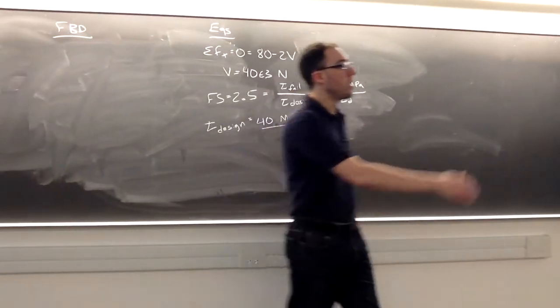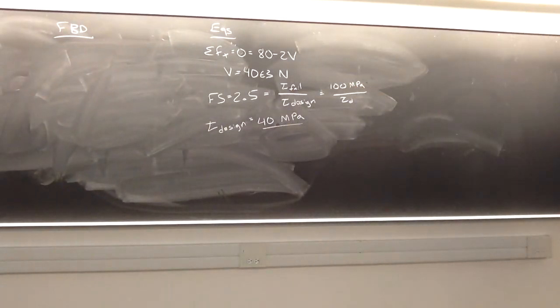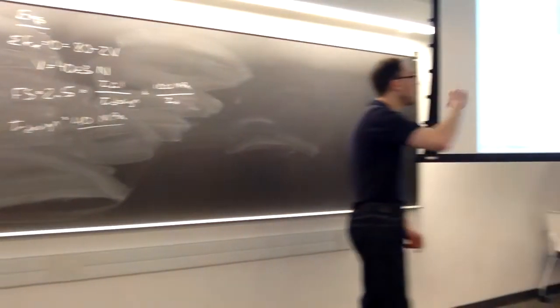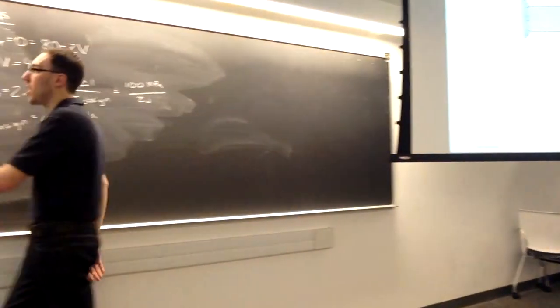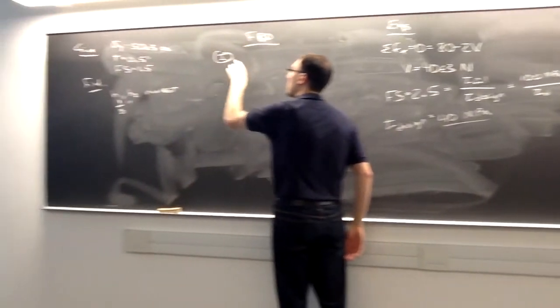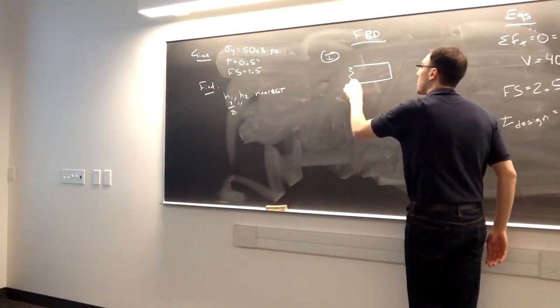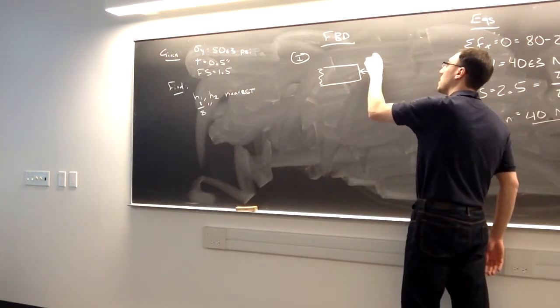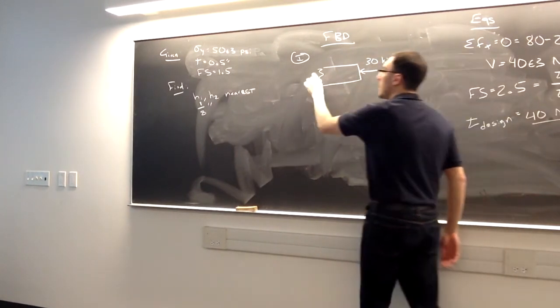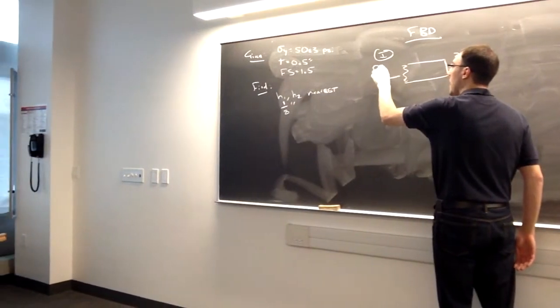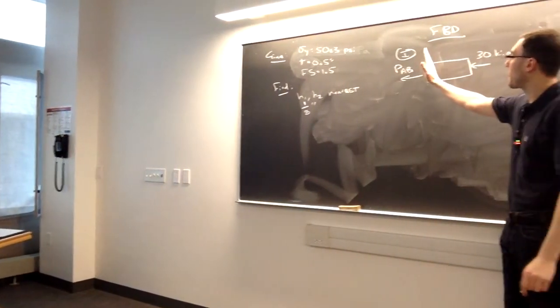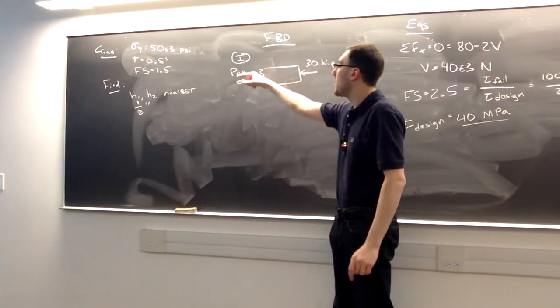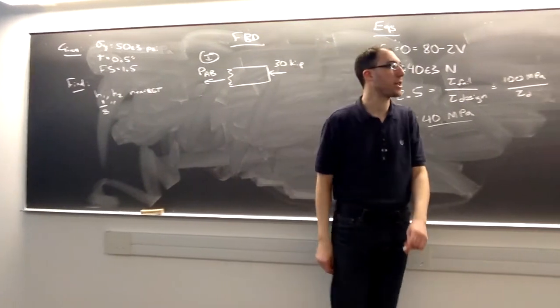If we drew the free body diagram cutting anywhere between A and B, that normal force is exactly the same. I'll just draw it here. For any cut we draw, we have 30 kips to the left, and the internal force, I'll call it PAB. It doesn't matter if we cut it here or here or here. That force does not change through the length of bar AB.